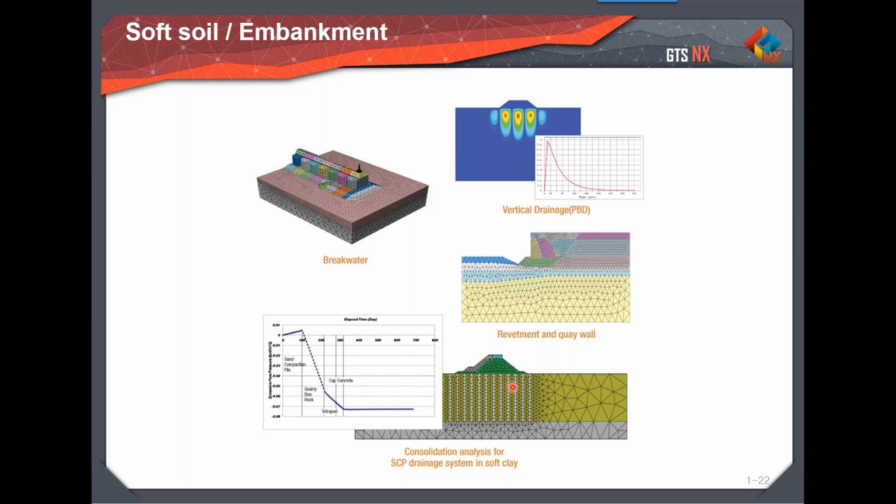So all such improvement techniques can easily be simulated, so that the settlement versus time, as well as the pore pressure versus time, can easily be understood, so that the consolidation behavior and the improvement scenarios are understood. And then this can be combined with your embankment, and embankment slope stability can also be checked before and after consolidation. So that's one of the applications.